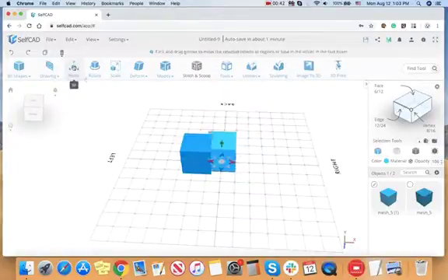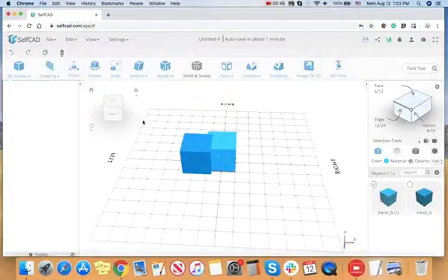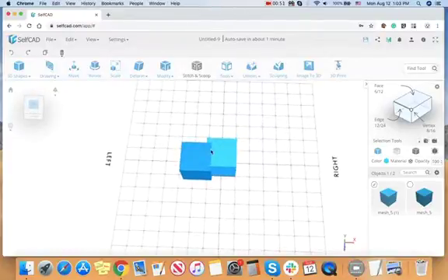I'm going to center one of the objects. This is selected first. Center means it's 0, 0, 0 position. So this is centered. Now, I want to align the other object. I know this is centered, and I know my gizmo position, my pivot point, was from the center. You can adjust that, but by default, it's the center of the object. So that means that if it's the center of the object, I measure only half from the object, because this is basically the center, half of it.